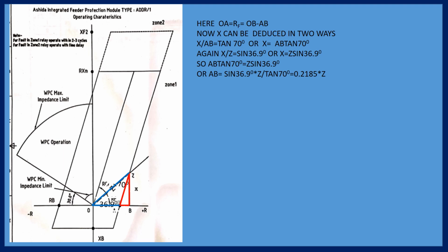So the same S1 is coming, but in the field, when you are connecting with the power transformer circuit on the 132 kV side, one direction is reversed. So we are connecting S1 with S1 and S2 with S2. Okay, but actually in the returning path it will be reversed. The current is reversed, then S1 S2 will be reversed.